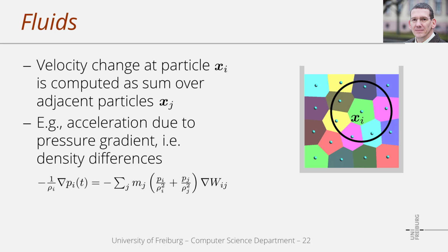The idea of such a discretization concept is to use information at a particle and at adjacent particles to approximately compute the spatial derivatives that are required in a force computation, which is typically the gradient or the Laplacian. So generally, forces or accelerations or velocity changes at a particle xi are computed as a sum over adjacent particles xj.